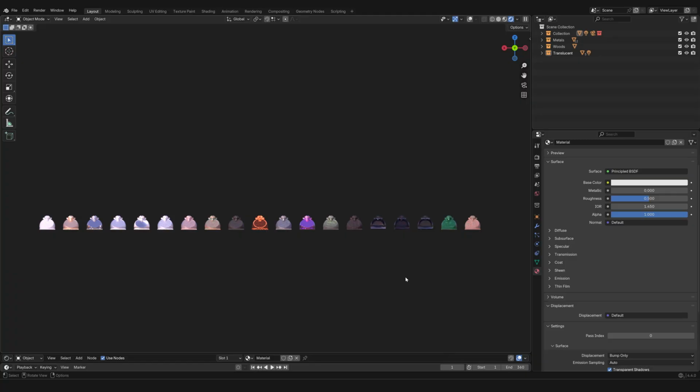So for example, when you have an HDRI or when you have texture images that are linked and referenced to your file, if you move those files, if you change the directory, if you rename those files, or if the project moves to another computer, then you will have a big pink warning everywhere. Things will go missing. And so to avoid that, you can pack the resources with the Blender file. And now everything that is within the file, it's embedded and it is with it wherever it goes.